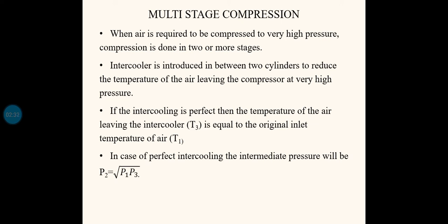So some coolant will be there. Of course, usually atmospheric air is used as the coolant. For some other purposes we will be using specially designed intercoolers, and some designed coolants are also used. Some cold water is also used. That depends on the situation. Anyway, an intercooler is introduced in between two cylinders to reduce the temperature of the air leaving the compressor at very high pressure.